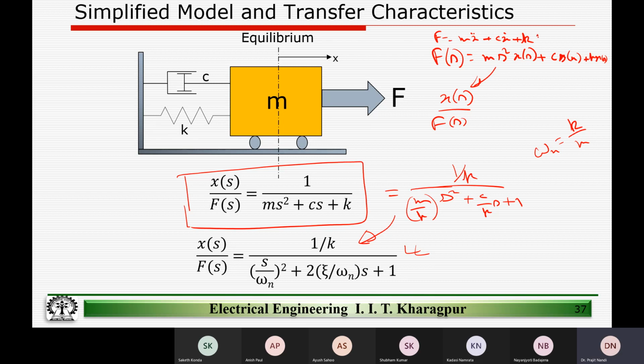So this kind of equation has a second order behavior. It inherently has an oscillation kind of behavior associated with it. The natural frequency of that oscillation, meaning if there was no damping, if the C x dot term was not there, if we release this and there is no friction or nothing where energy is dissipated, then this will behave as an oscillator. So that natural frequency of oscillation is given by omega n.